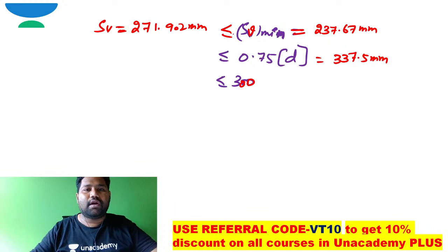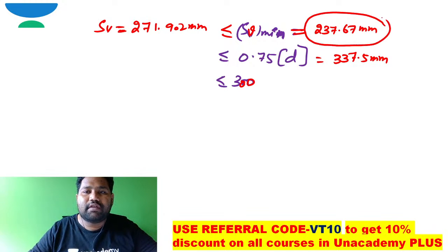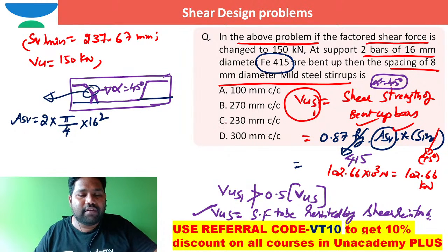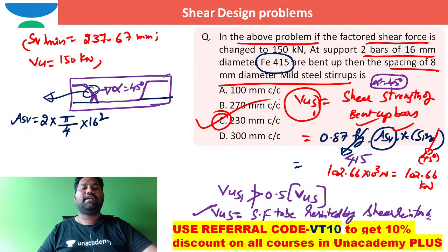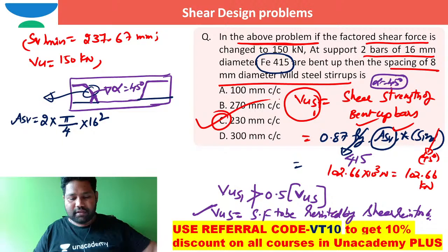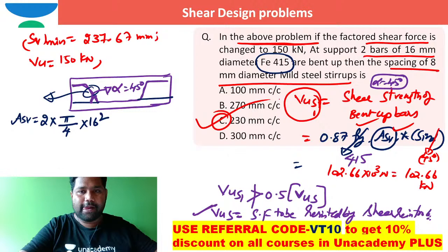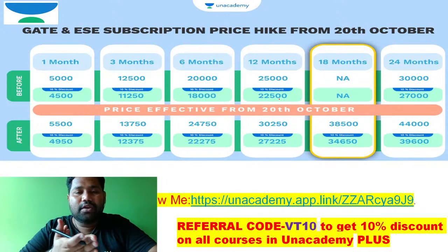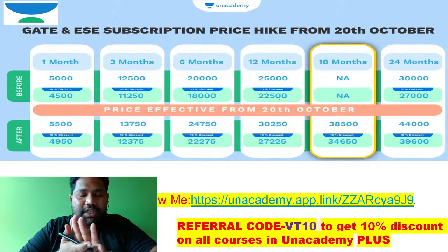So we got these answers. Out of these, the minimum value I need to take. The minimum value is 237.67. So for this problem also, the spacing you can keep is 237.67. What is the answer that is nearest to 237? It is 230 millimeter. So 230 millimeter center to center will be the correct option for your problem, right? So we completed the numerical questions on this shear.